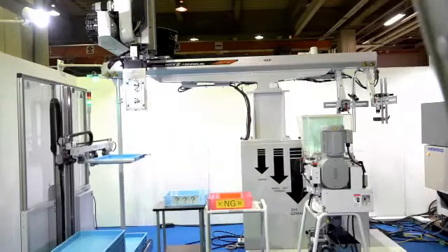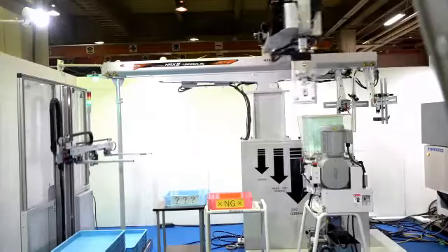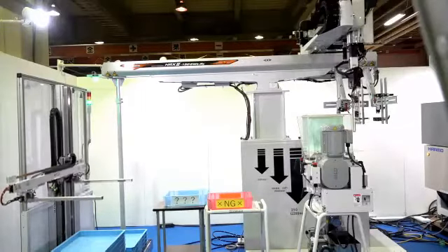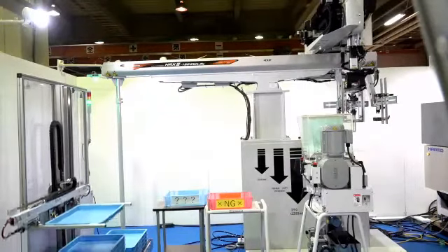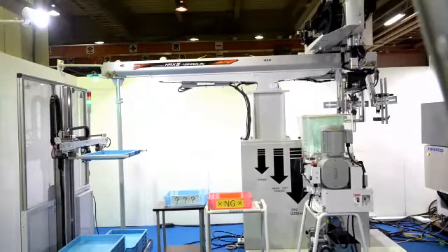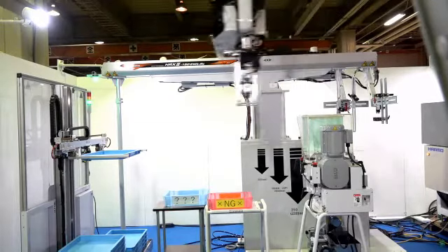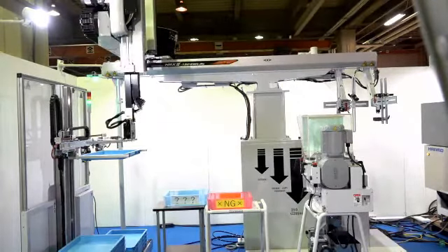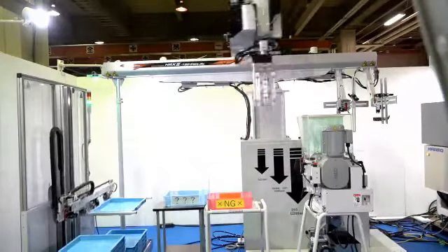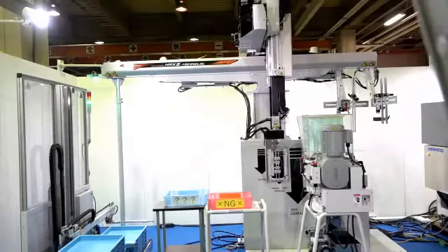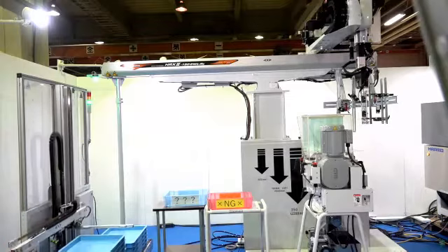If the machine is stopped completely with the error, to restart a whole equipment takes a lot of time and energy. It is possible to solve the problems with Total Link without stopping the operation. Production defects can be separated to two places, inspection place and defect place. Also, you can set how many times the robot releases the product to each place. Of course, if the error isn't canceled within decided times, the robot stops its operation with the alarm.